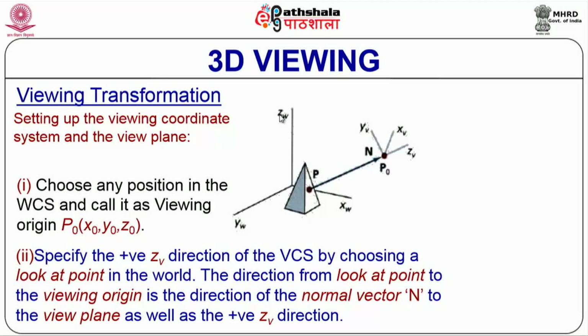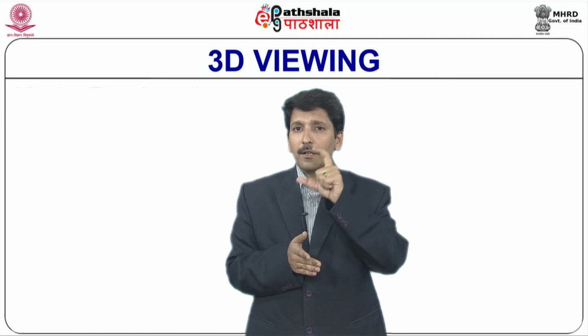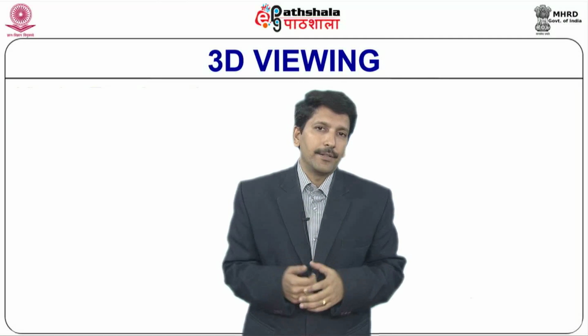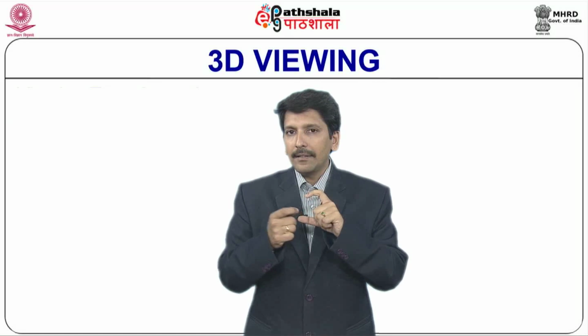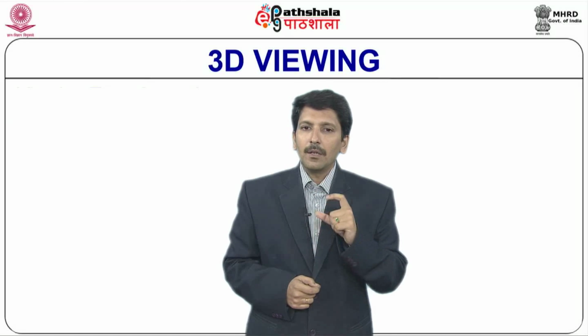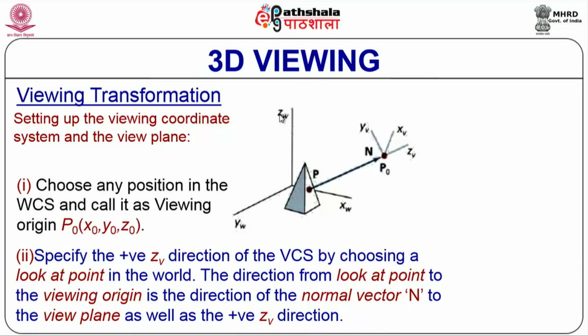Then we take a direction that is perpendicular to the z and y. Once we have the y direction, which is a projected direction, and the z direction, the direction that is perpendicular to y and z will be the x direction. Directions perpendicular to a plane can be easily obtained by considering two vectors within the plane and taking their cross product.